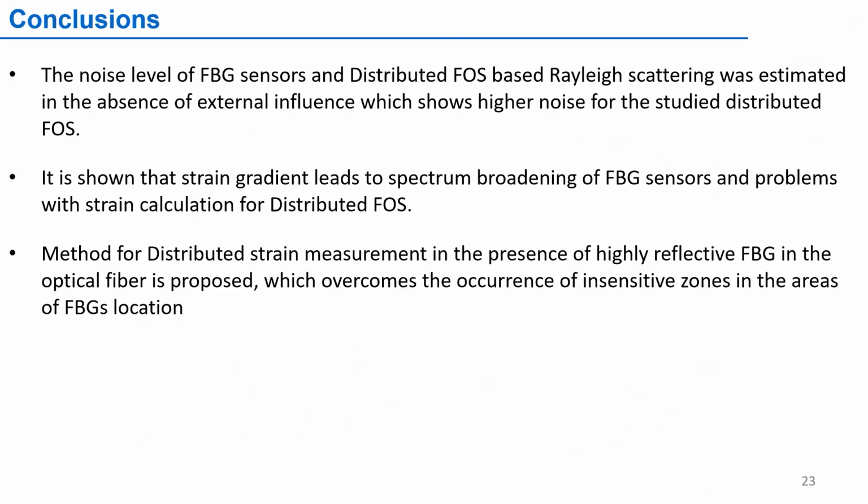So in conclusion, the noise level of distributed fiber optic sensors and fiber Bragg gratings was estimated, and it was shown that strain gradient leads to spectrum broadening of fiber Bragg grating sensors and can be optimized for distributed fiber optic sensors, and a method was proposed to measure distributed strain in the presence of fiber Bragg gratings in the optical fiber.